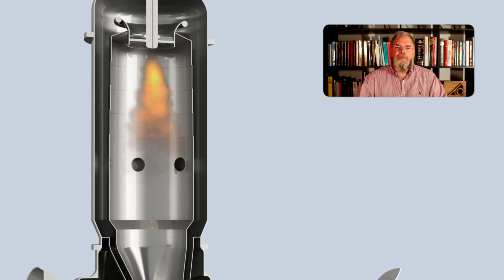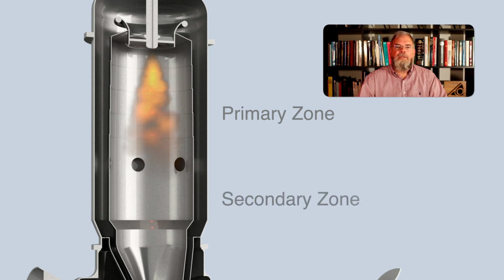Additionally, for flame stability across the full operation range of the engine, the mean equivalence ratio of the primary zone is higher than the mean equivalence ratio of the full combustor. A large fraction of air bypasses the primary zone and is mixed with the exhaust gases from the flame in the secondary zone to reduce the high temperatures of the primary zone down to the turbine inlet temperature. The result of this is that diffusion flames produce relatively high NOx emissions.